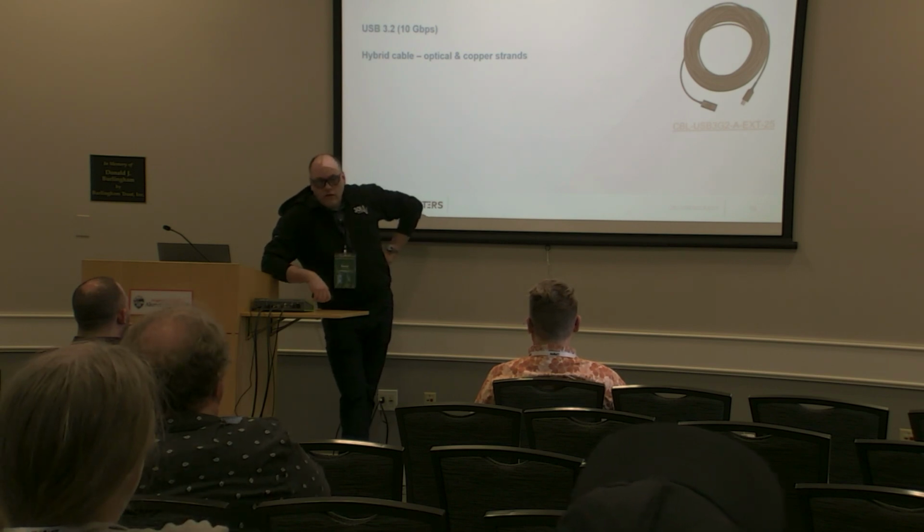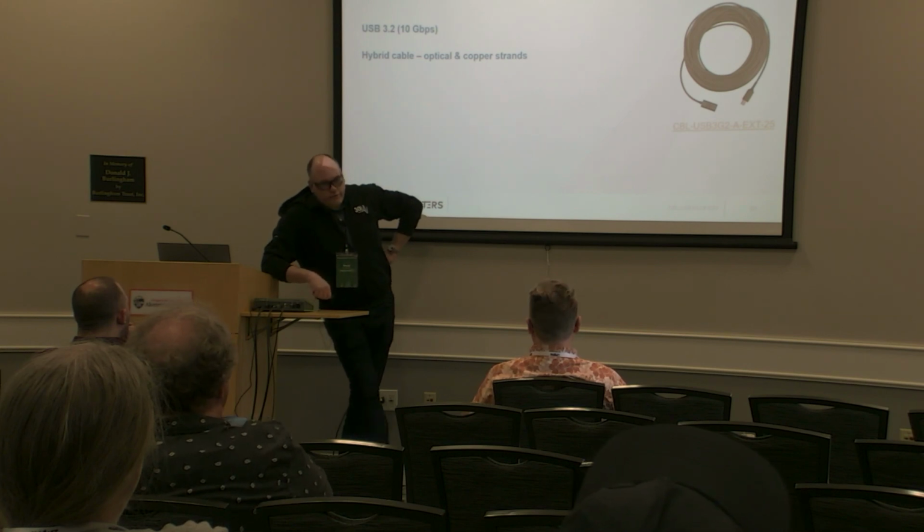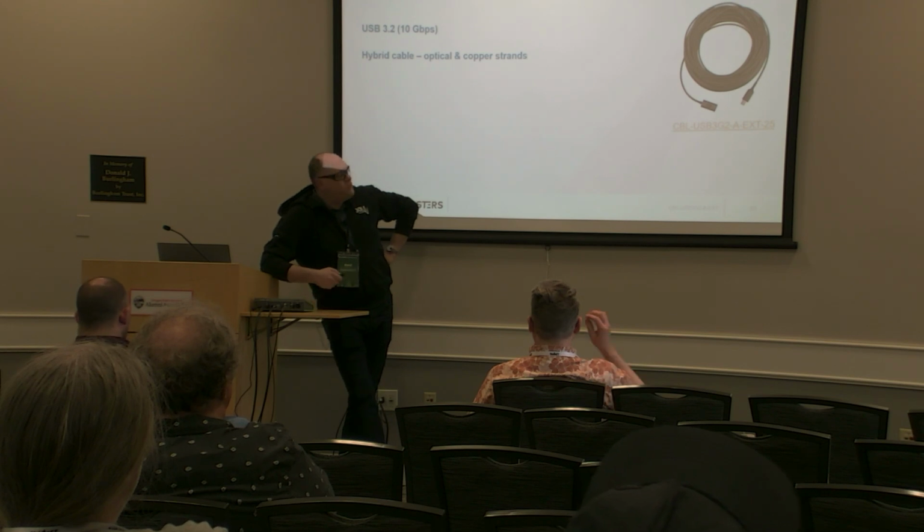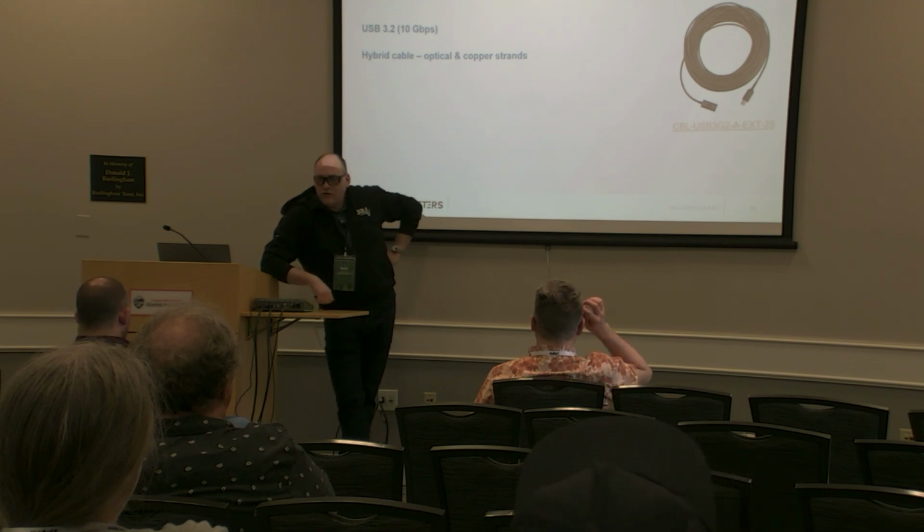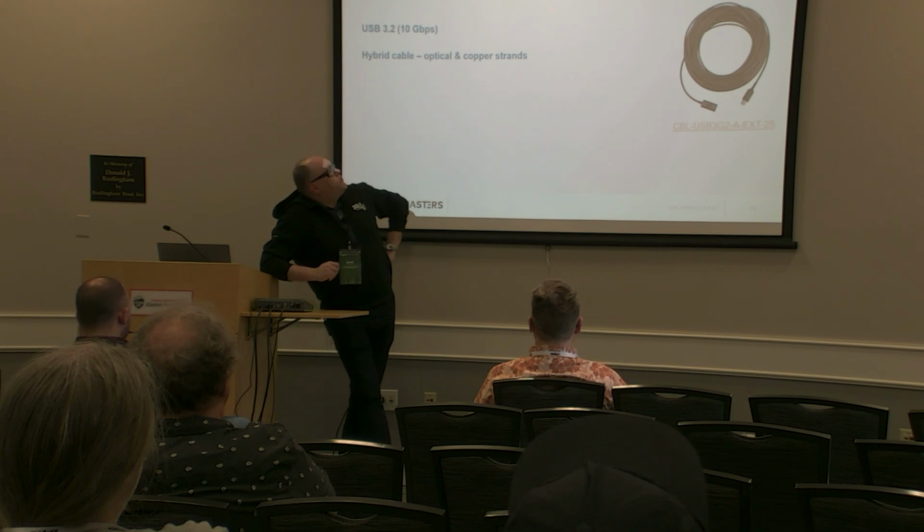Does that count as a hop? No, it does not, because it's just reclocking it. It's not actually a host controller in there. So this is not spelled out in the specs, but it's something I want you guys to know. I tell people this is the default cable they should use when they're doing USB extension, because you can get up to 150 feet. It's a fiber optical cable.